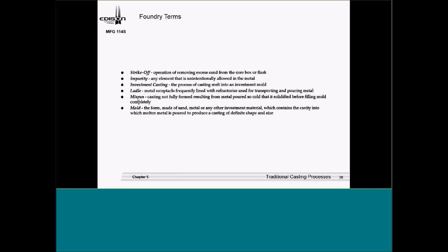And what I'll end up doing is that we'll break off what we have and I'll have the student just repour. And again, what I'm looking for is that they do pour a casting that's satisfactory. And if we mess up, we don't have the sprue right, we don't have the riser right, they'll generally have an opportunity to go ahead and try the process again.